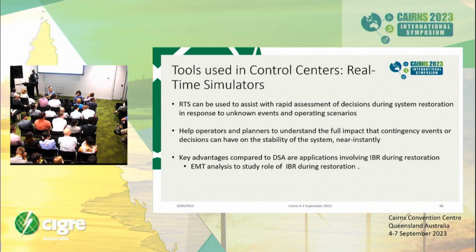I have seen all the traditional approach here. In the future, black start will be very different. Maybe, hopefully, they will not be so black, because with a lot of distributed resources and active portions of the distribution network, we will have a lot of islanded operation possible. This can help a lot, but it's not straightforward, and the restoration of the network has to be studied. I understand this group did not consider this. Maybe it can be a recommendation for future work, or did you analyze it also?